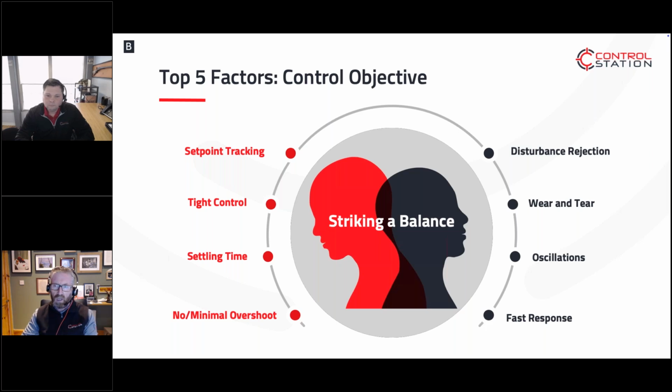It's something that actually drifted in again from our survey at the start, that 50% run tuning in manual. The likelihood is that's one of the fundamental reasons why it was working and now is not working, because the process has moved in one direction or another, or equipment has started to age, it's getting sticky, the heat exchangers are scaling, or something has changed to cause the process to move. And the manual tuning efforts tend to leave the process right at its edge, similar to the Ziegler-Nichols.